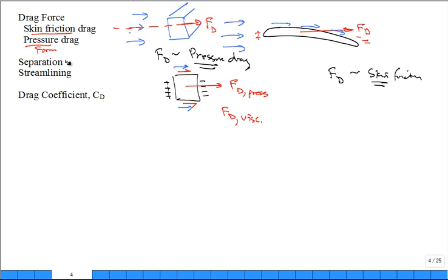So what is the difference? A lot of it due to separation or the lack of separation. When you have separation, what's happening is the flow stream isn't staying in contact with the body. And so if you're coming over this cylinder like this, you're going to have a hard time because the fluid's coming here and it's going to want to turn up. This fluid wants to turn down. This fluid way out here just wants to keep going, right? But this is now going to want to push off, and then you're going to want to be turning it. It's going to separate right there. Maybe it'll reattach later, but it'll separate. That'll be a point of separation right in here. And then coming around here, it's going to want to try and fill in here, but it'll be a big separation region in there.